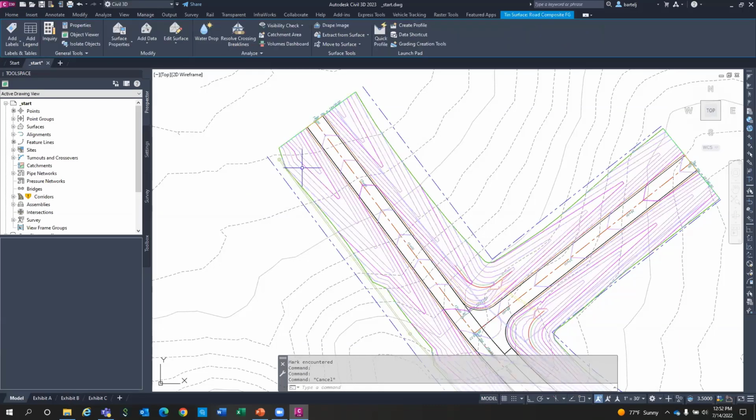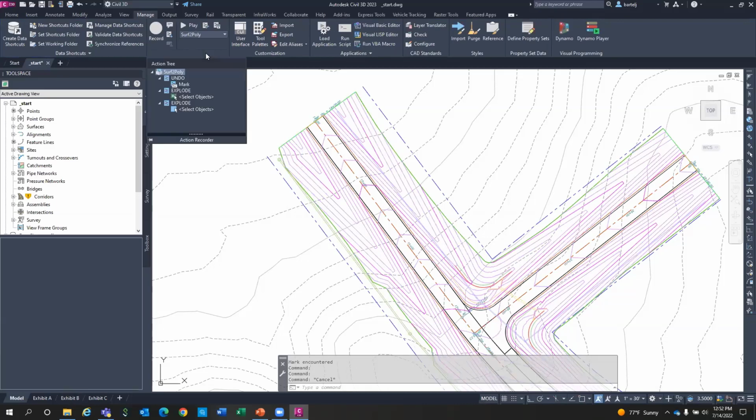And then if we were going to test this particular command, now, first thing, if we're going to test the command explode, when it says select objects, remember, it's not remembering an object, it's remembering a pick off the screen. If I want this to be portable, where I can use this in other files, remembering the coordinate of where this surface is isn't going to help me. What I'm going to do is right click here, and say pause for user input.